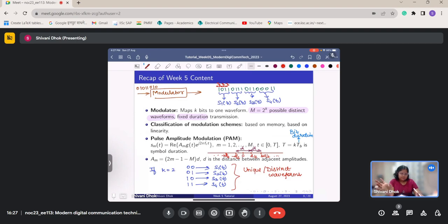Due to that sampling frequency, in each second we have a particular number of samples coming up, and each sample is quantized to some discrete level, which is then encoded to bits. So due to the sampling frequency and the number of samples generated in a particular second, we have a particular time required for generation of this particular bit, and that is known as the bit duration.